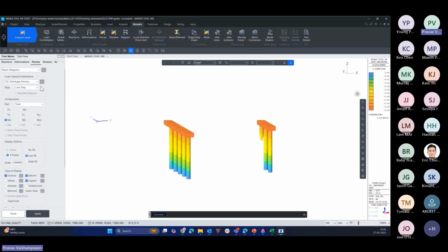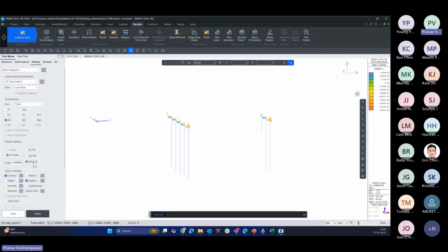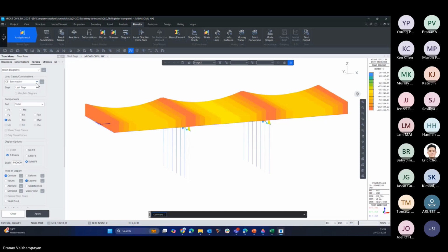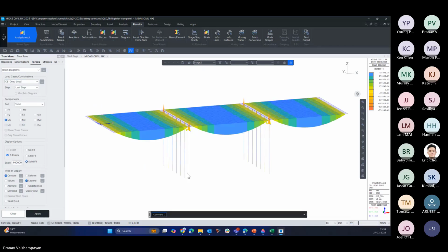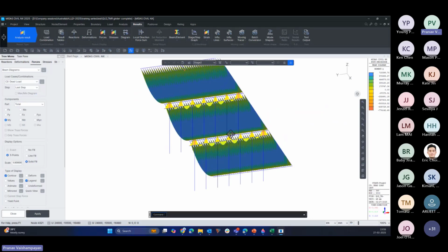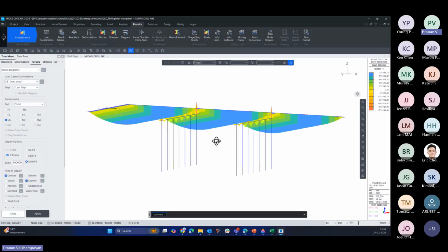So again, stage 1, bending moment. I'll use the summation option. Turn off the deformation, calculation apply. Stage 2, when the girder is active, you just look at the dead load. You can see pure sagging and the cross beam is acting as a continuous beam.